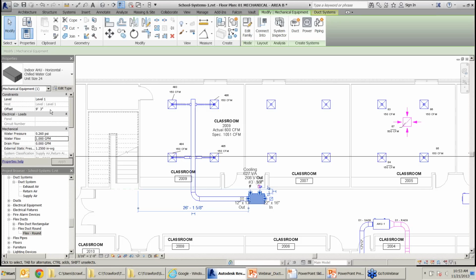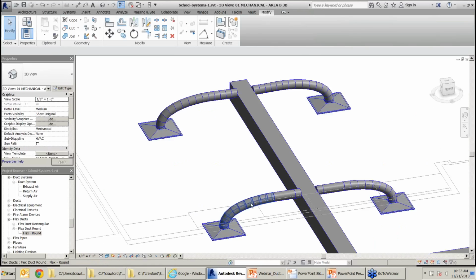these ducts. Do they need to be 10 foot? Maybe I need to raise up that equipment. Actually, I do need to raise up this air terminal, or it's an air handling unit. So if I wasn't talking, if I wasn't demonstrating, I should have taken a look at that first. If I raise that up, then this should work out quite a bit better. Shoot. If I had a little more time, I would do that. And then it would work much better.